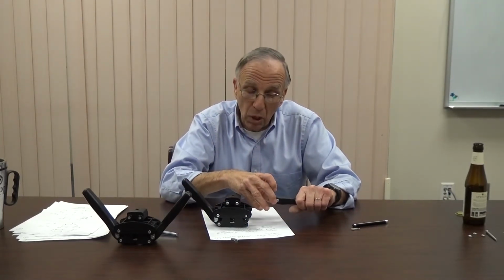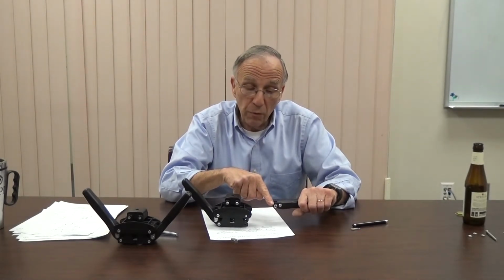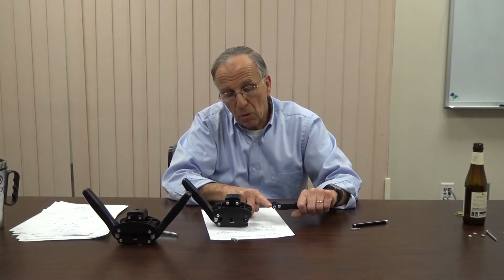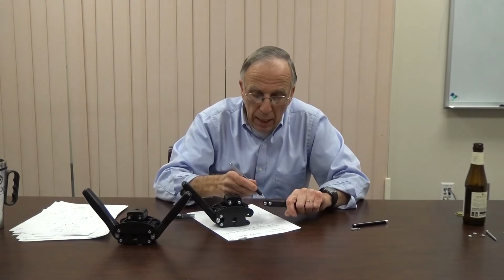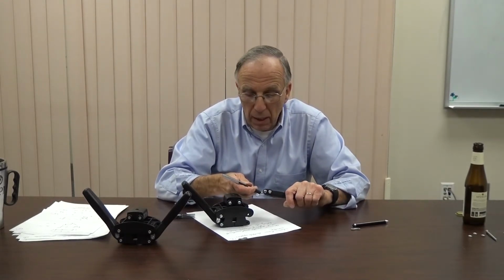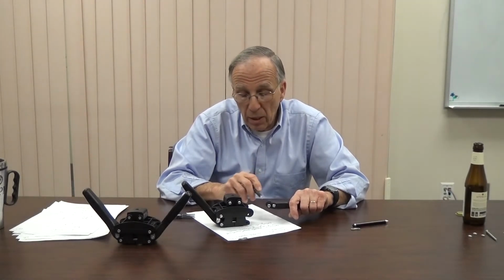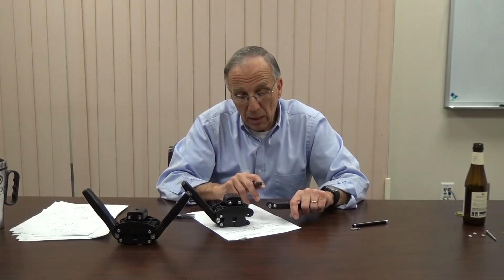We can have pull out, which, depending on how this would fail, could involve, if it fails by pulling out along a piece that's the same width as the diameter of the pin, then that would be a shear failure. On the other hand, if the whole piece fails by breaking this part and this part, then that would be a tensile failure in this material. So you can see that we have a number of different types of calculations depending on how this mechanism fails.